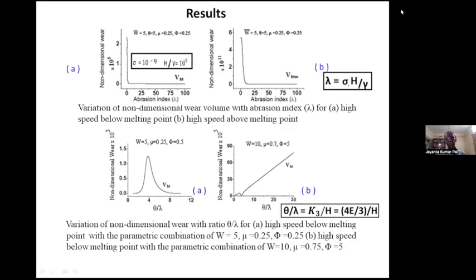But there is one thing we should remember here: for adhesion to be large, the roughness given by sigma, the standard deviation of surface heights, should be at the nanometric level, 10 to the power minus 9. And for most polymers, H by gamma is of the order of 10 to the 9.